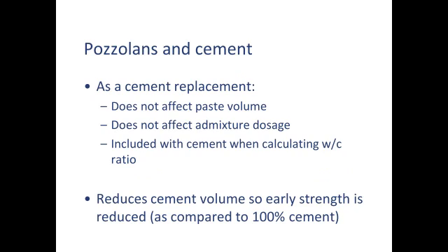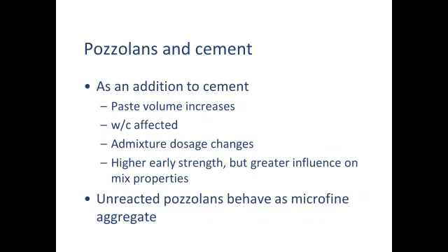The downside is, as I replace more and more of the cement with pozzolans, I take away the cement that provides the early strength. So high cement replacements yield low early strengths because there's not a lot of cement to hold everything together. You can also add them.